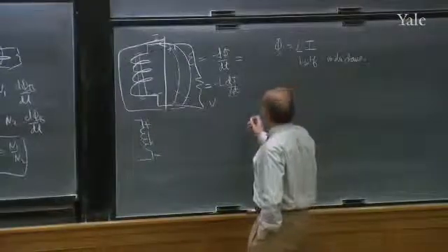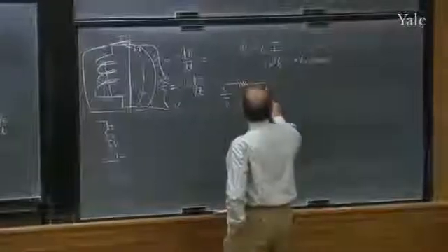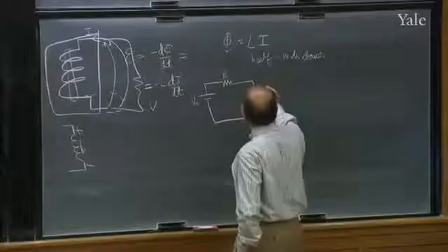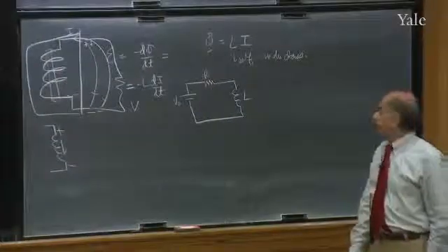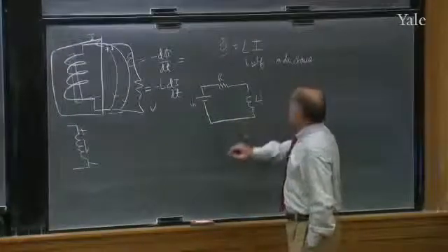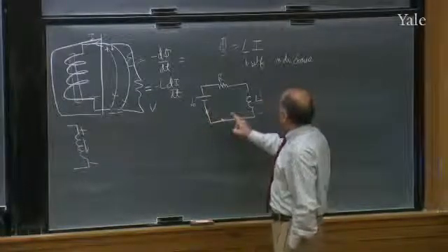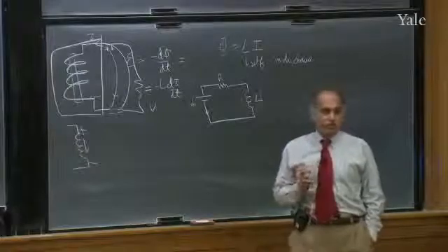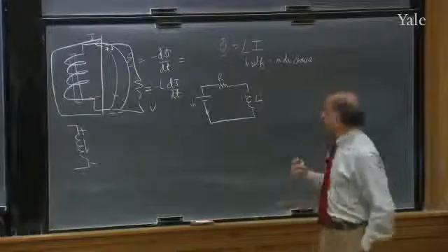So we can have the following very simple circuit. We have a battery here, we got a resistor there, and we have an inductor here. This is some voltage V, this R, this is some L henries. So let us write a circuit equation, and here is where I spent an inordinate amount of time justifying what I'm about to do. I say start here. There's going to be voltage defined everywhere except inside the black box. You understand you cannot define a voltage inside the black box where there's an inductor because there is a non-conservative electric field inside. But we promise not to go there.